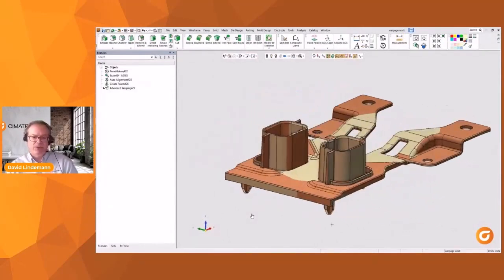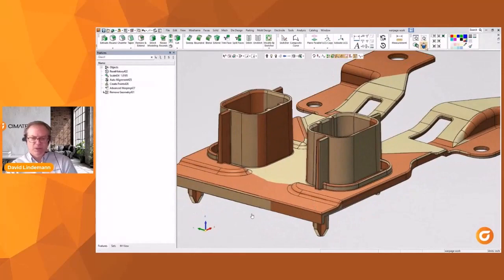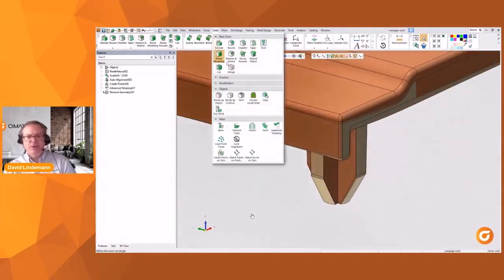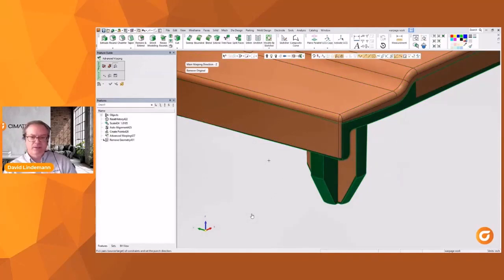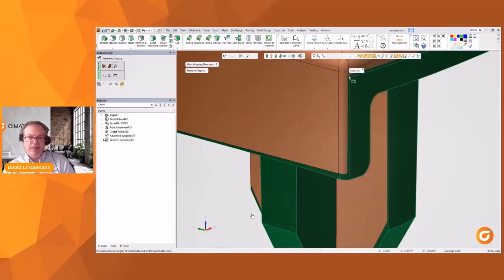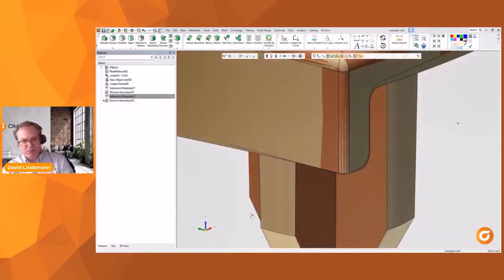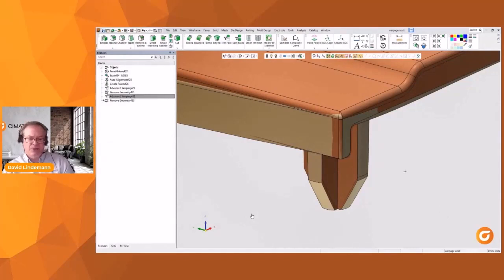Let's say down here in the corner, it's warped considerably, but I need to maintain something right along the parting line. That's something that the customer insists I hold for whatever his design conditions are, and I could see it's slightly out here. Even after having gone through the big version of the software where I point all these points, I can now go back or just simply grab a point on the part and snap it back to the original. So maybe along this back wall, I'll say at this point, snap it up to that point. That's straightforward, and I'll see it basically bring that whole part into that position. So it's just nudging it for me to line those two up.